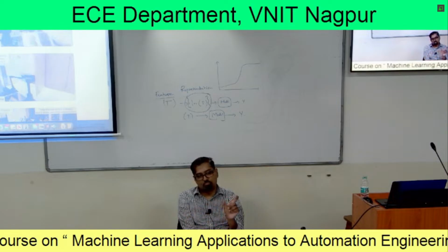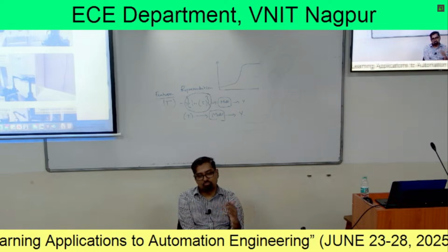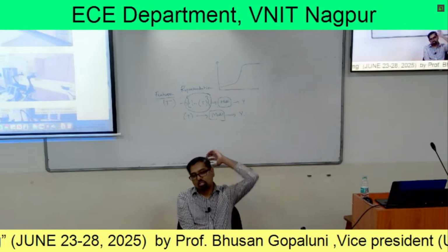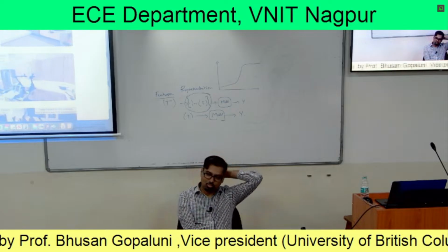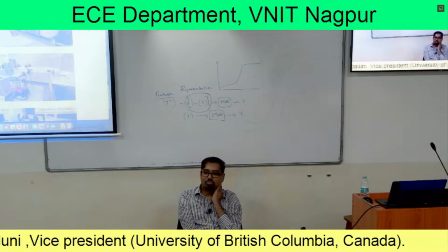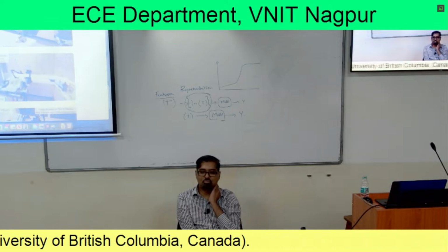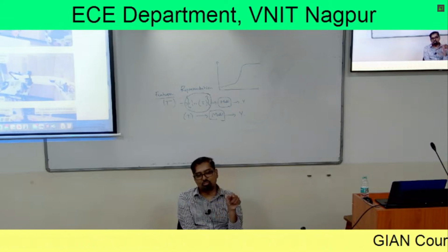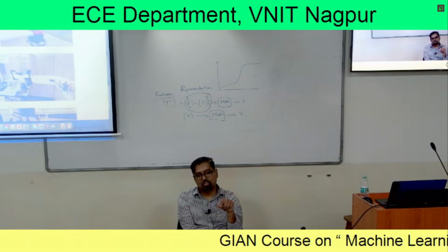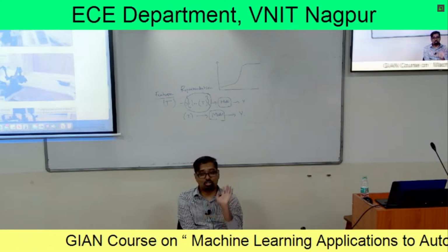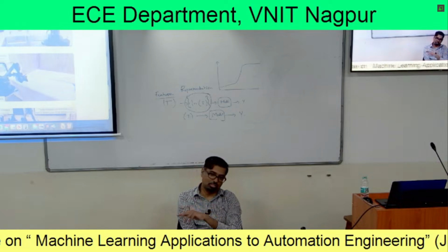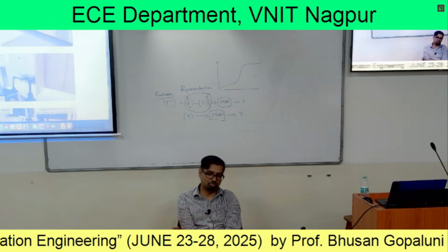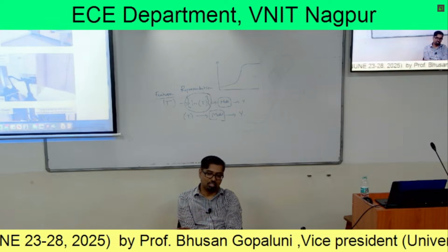If you look at traditional control algorithms, not the adaptive control algorithms, they're not self-tuning. You tune them once and then you just sit back. If the performance drops, then you trigger auto-tuning. I think the advantage that reinforcement learning has is that you don't need to do that. You just turn it on and then you can sit back. It's always monitoring the performance, and if it needs changes, it'll generate some data and retune the controller all by itself.